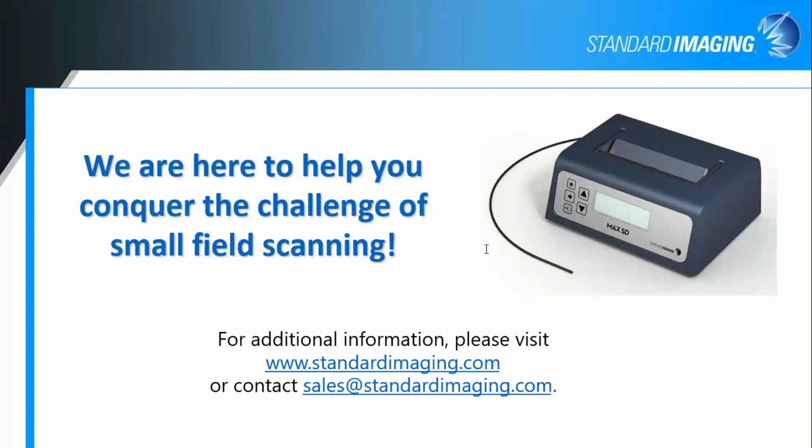Otherwise, if you've got some background signal, it basically causes your low signal measurements to look higher than they actually are, because you start bumping up against that noise floor or against that background signal that hasn't been zeroed out if you're not zeroing your MAX SD and your scanning tank. So that's the first thing I would check is your zeroing.